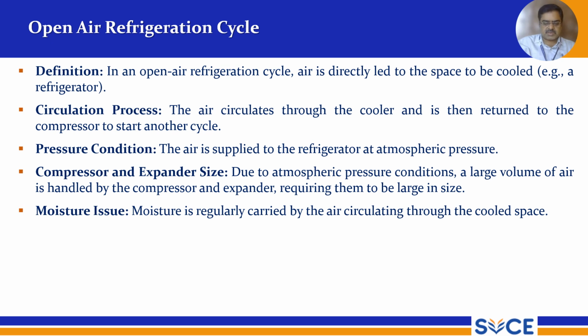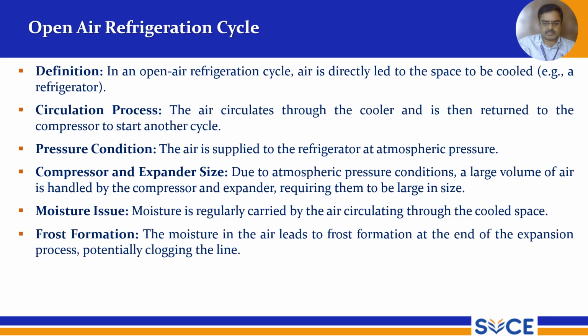Moisture issue is there because air always contains some humidity, and moisture will form in the air. Moisture is generally carried by the air circulating through the cooled space. The frost formation issue is also there. The moisture in the air leads to frost formation.